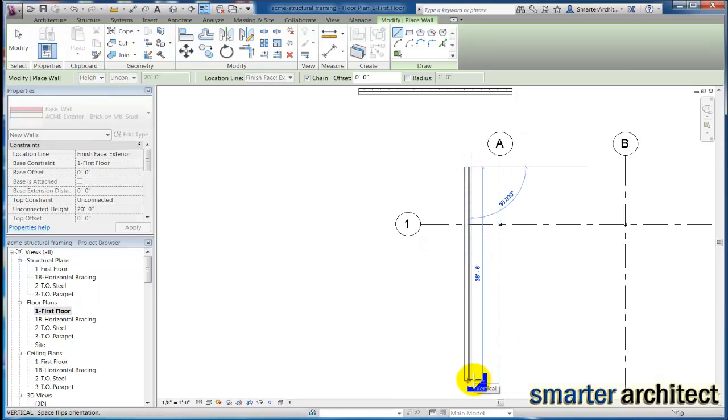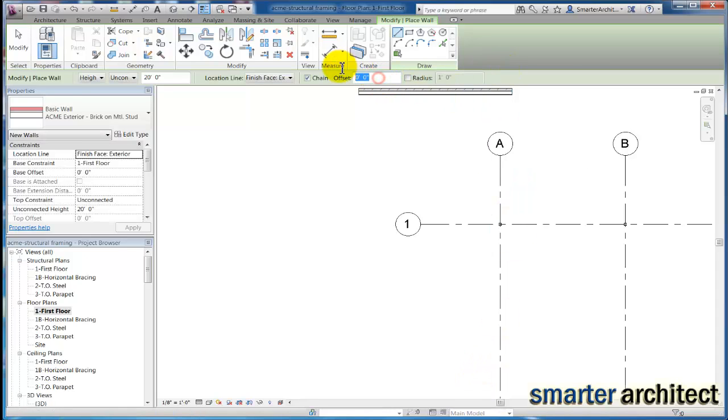One, I do know we have an offset. If I wanted to start laying out this wall from the column grid, I know that we have an offset of 1'5". So if I give myself 1'5" in this offset category, and just begin to select this wall even, we're going to take this wall up to top of parapet.